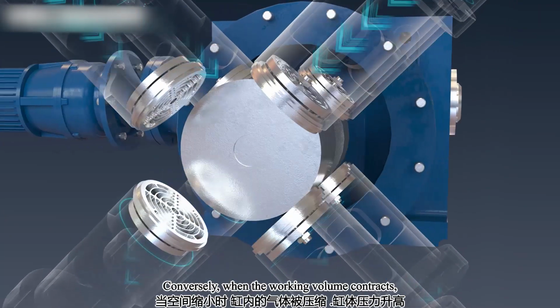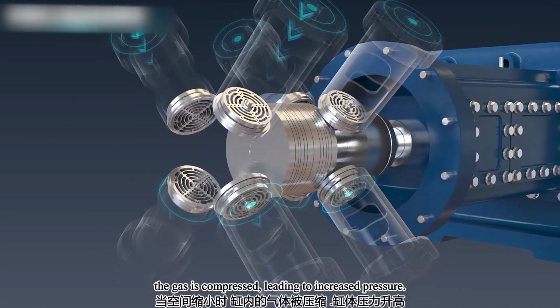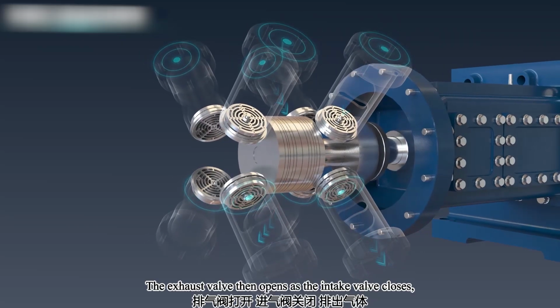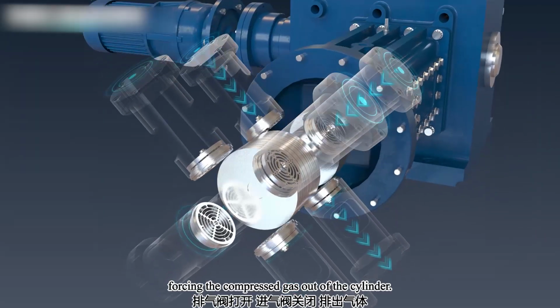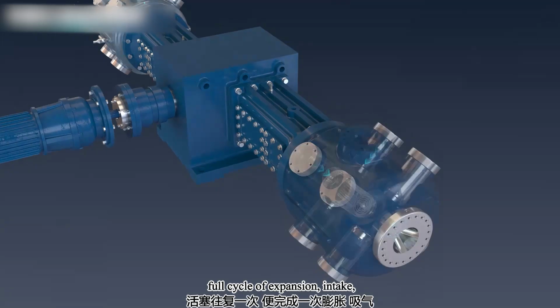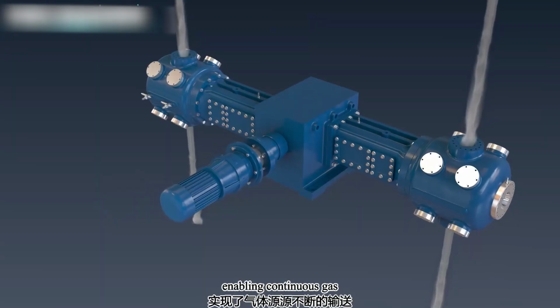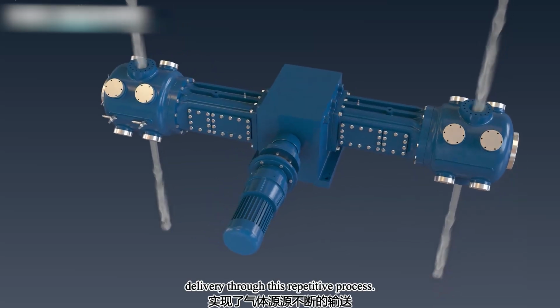Conversely, when the working volume contracts, the gas is compressed, leading to increased pressure. The exhaust valve then opens as the intake valve closes, forcing the compressed gas out of the cylinder. Each piston stroke completes a full cycle of expansion, intake, compression, and exhaust, enabling continuous gas delivery through this repetitive process.